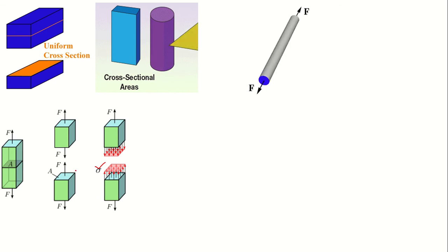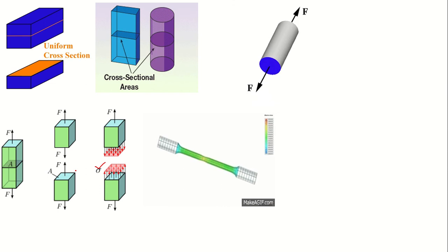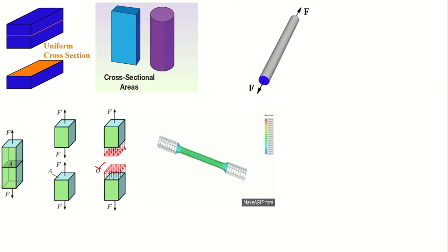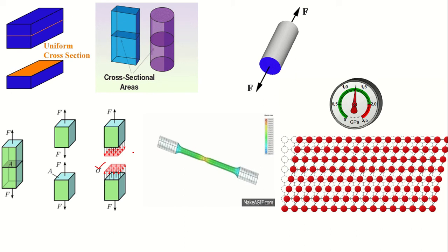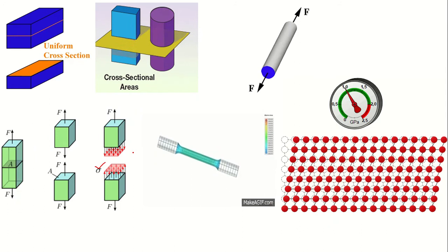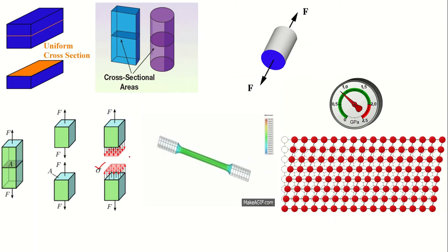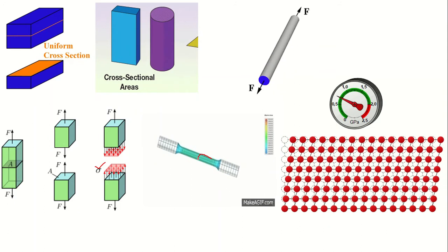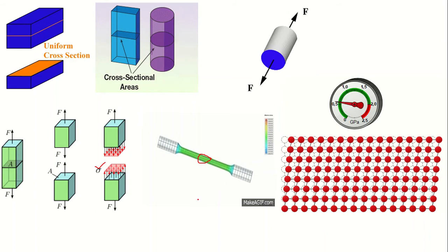If you take a circular bar, look there, the two forces are actually applied opposite to each other. It is called tensile stress. Okay, so this is how the stress will act. What happens once the force is applied here? What about the molecules? Please observe here. This is how the molecule dislocation takes place. This is the reason why in ductile materials you can observe this type of necking formation. Now, what is stress, guys?